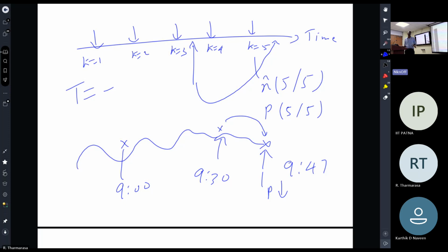The reason is that because of the process noise, this information may not be relevant at this point. If the capital Q is 0, then both may have similar information. So there's no uncertainty. You can predict and come to that, right? So that means when this gap increases, the benefit of this in updating diminishes. So after a certain point, I can throw it away. I don't need to go through a hard update step.